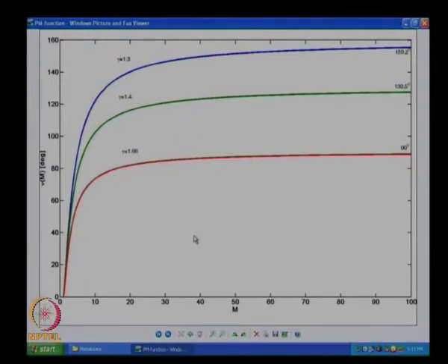This is the speciality of hypersonic flows. When Mach numbers are above 6 or 7, most of the variables start tending to become constant. We will deal with that more if you are doing a course on hypersonics, but we will just leave it with supersonic flows. Ideally I would zoom in only from 1 to 5, but I am showing this because I want you to note that they all go to an asymptote somewhere far away. After some time they will all go to some constant.